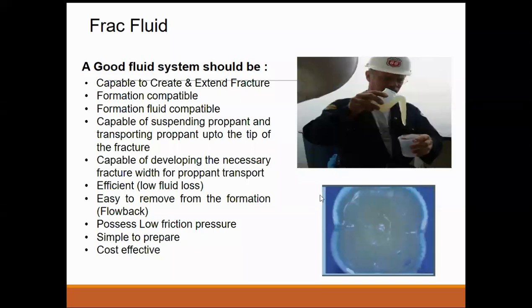The compatibility is to be checked every time you use a new fluid, or before you even prepare it. There are core samples which you take during drilling. So you should check the compatibility of the fluid that you're going to use with those core samples. Okay. Now it should be capable of suspending proppant and transporting proppant up to the tip of the fracture.